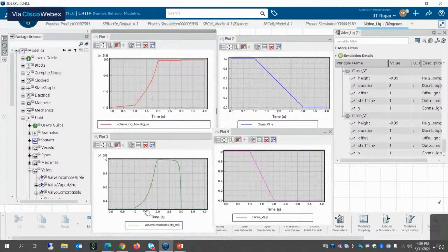And the fluid flow is something like this, and this is what the pressure drop looks like. And the volume flow occurring in the component itself is something that looks like this. So you can use this measure component and see how the fluid, so initially the fluid rises, and then once the valve opens, it flows into the volume component. That is, once the first valve opens, flow goes inside it, and at the same time the other valve also opens at 2 seconds and this volume starts flowing out of the system. So this is how one of the fluid circuits can be simulated.